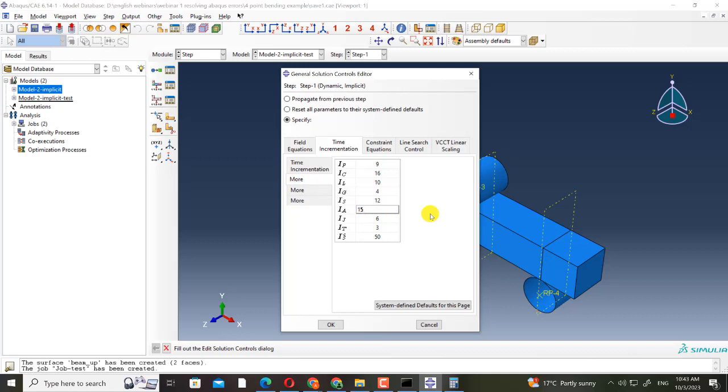You must resolve the other issue, and I will talk about all of these. For example, for a damage analysis or a crack propagation analysis using the XFEM method, the best value can be 10 or 15.